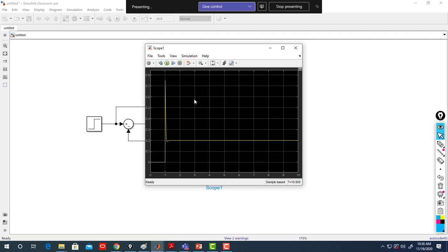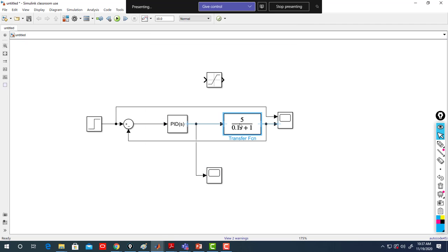So I want to point at my control signal. I want to put a saturation at 0.5. So then, assuming my signal will saturate at 0.5 or 0.4, then here I will be adding a saturation block. Okay.